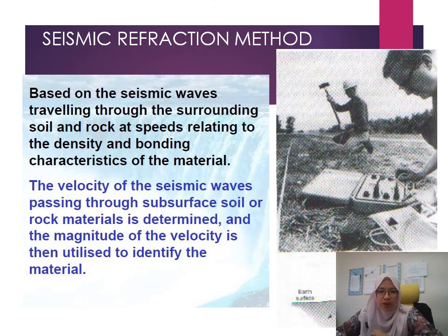For seismic, we use a hammer. This is the hammer, and now we are going to generate the wave. There is a steel plate here, and you blow the hammer onto the steel plate, and then a wave will be generated.